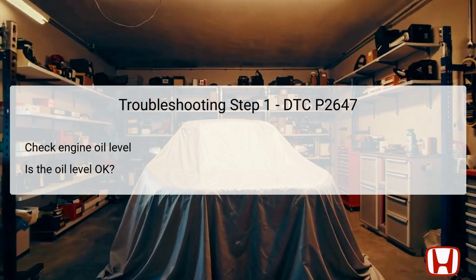In this scenario, if the oil level is low, the immediate action is to refill the oil to the appropriate level and subsequently proceed to step 11, as indicated in the diagnostic instructions. Conversely, if the oil level is satisfactory, the technician should move on to the next step to continue the diagnosis effectively. Monitoring engine oil levels routinely is also an essential preventive measure to avoid such complications.